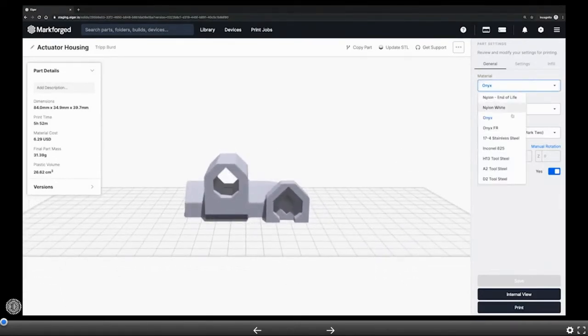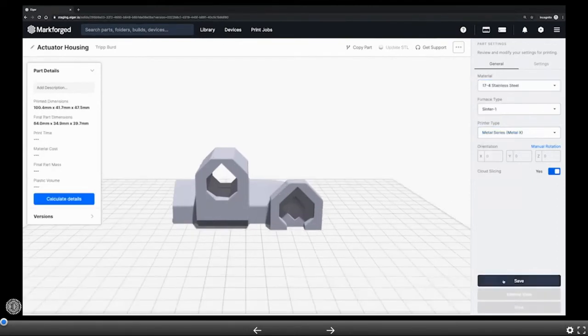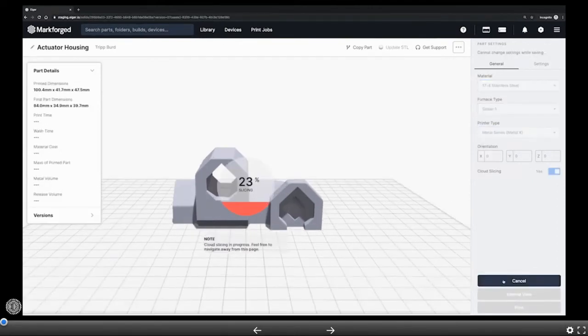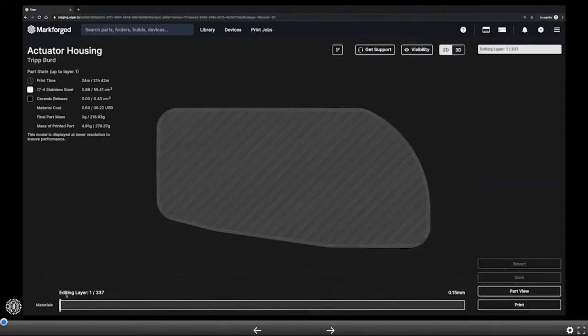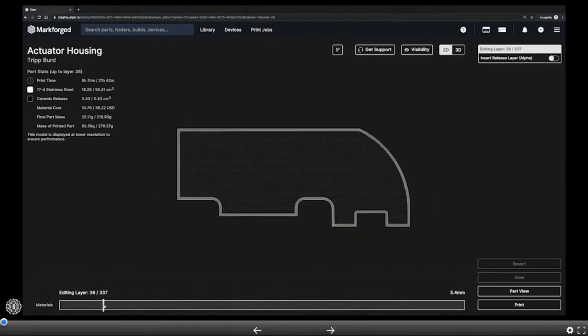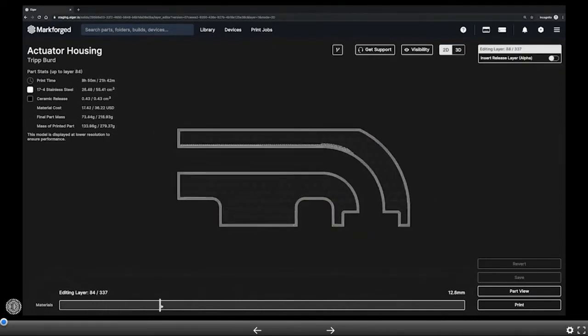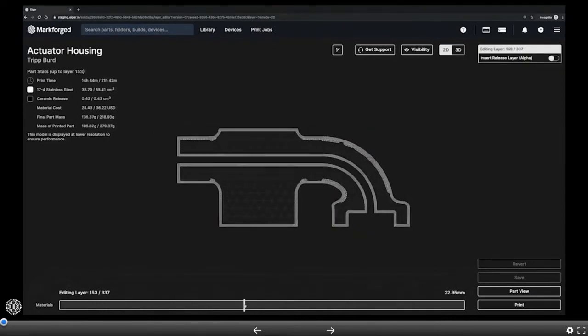When your part slices for metal 3D printing, it gets scaled up to account for shrink and deformation in the downstream processes. It then slices your part into discrete layers, identifies overhang features, and builds supports and a raft underneath your part. As we go through printing, washing, and sintering, Eiger will monitor the part's progress along the way. Let's start this print and go to the Metal X.